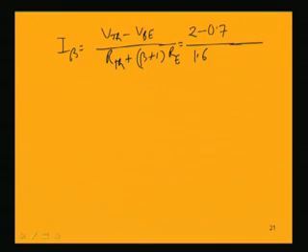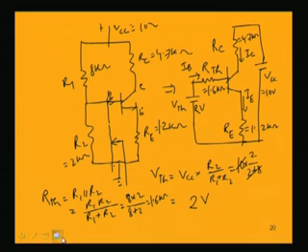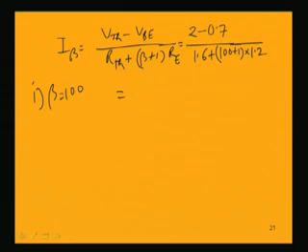I am keeping all this in K and this voltage is in volt. So, finally the current expression will be coming in milliampere. So, 1.6 plus beta. Now, first case beta is 100. Let us take that 100 value, find out what is the current. RE is equal to 1.2 K into 1.2 K. So, this value will be coming to be 0.01059 milliampere, or multiplied by 10 to the power 3 in order to write in microampere. This is milliampere. So, 10 to the power 3 if we multiply, it will be 10.59 microampere.